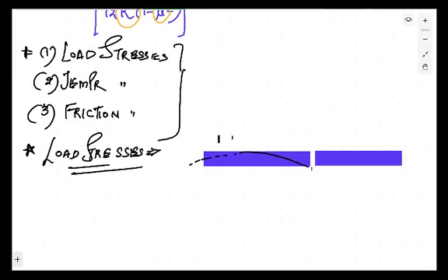The slab will try to attain a shape which is something like that. Now, this is the nature of the slab: if your load is applied over the slab, because of the presence of joints, the slab will try to hog. This is known as hogging. You have already completed this topic in the strength of materials part: when you apply the load like this and the supports are present at the center, not at the corner, because the corner is open because the joints are present, then the slab will try to hog.